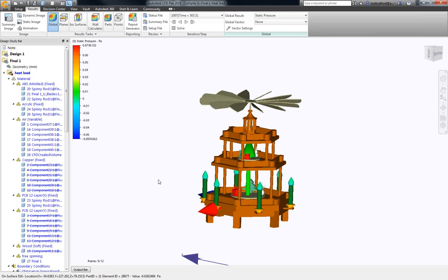Our CFD tool is a finite element analysis program, meaning that it solves at the nodes of the elements. And there are other commercial CFD codes that do the same thing. There are also commercial codes that do finite volume analysis, where you're solving for the fluxes at the faces of the elements. Now, if you have a tetrahedral element, that's going to limit how many faces you can interchange material through that volume. That's why you'll see, for instance, hexahedrals used in other codes, because they increase the faces, which gives more flexibility to the directions that flow can go.